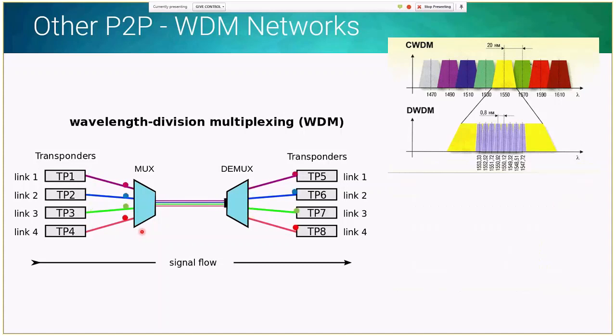This is important for massive data rates, and if you want to use the full bandwidth of the fiber, and this is what we start seeing now. So if you're going to the CWDM, we will see that it occupies not only one window, but it will occupy 5 windows. So it will occupy the O band, E band, S band, C, and L band. And this is what the spectrum will look like.